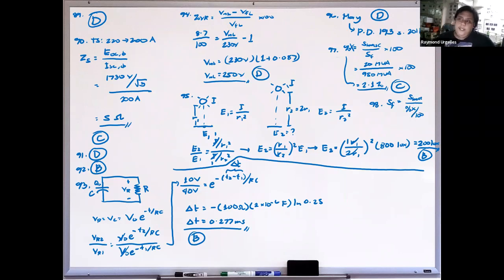So if your reactance is larger, your fault power is lower. What the series reactor does is increase the reactance, hence our fault becomes smaller. So this is to bring down the fault level within the capacity. So this is letter C. Next, number 99.